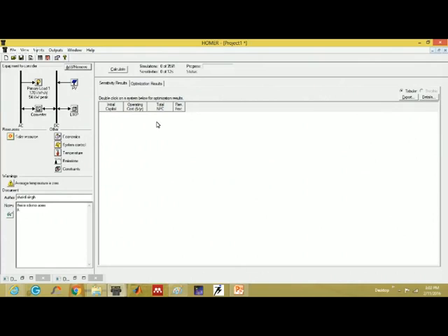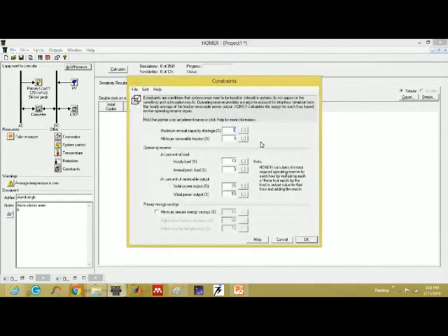You can go to any mathematical presentation of data. That's the mathematical part. As constraints, you can give a maximum annual capacity shortage of zero, or a minimum renewable fraction. Let's say we have a system where I am putting diesel also, and I want at least 50% of power to come from renewable sources, or I want 100% of power from renewable. So I can give that fraction.